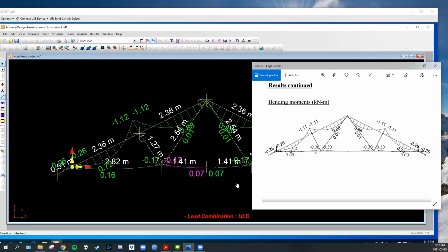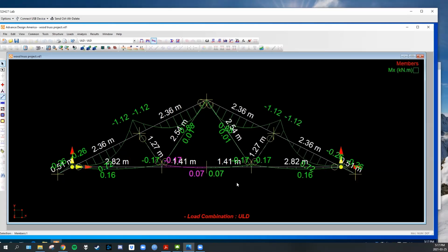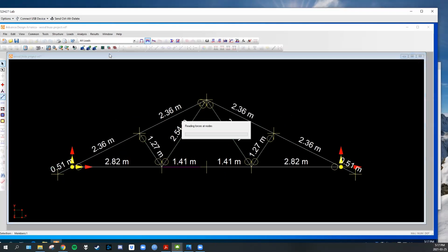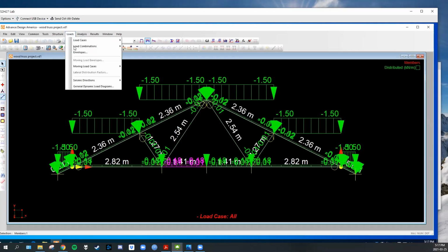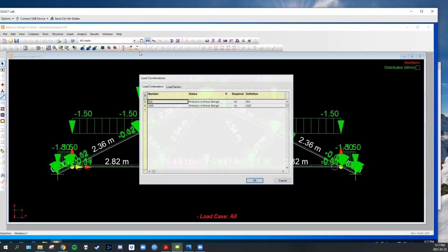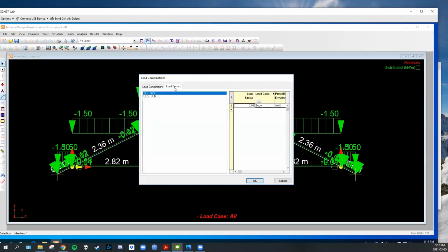Let's see what the difference is. Alex, did you add the self-weight of the truss in your analysis? Yeah, I believe so. Let's take a look at that. No, you've got to go to load combinations. Yeah, that's good. Go to the next one. Ultimate, 1.25 your dead load. Yeah, you've got them all in there. Okay, so at least we know that's good.